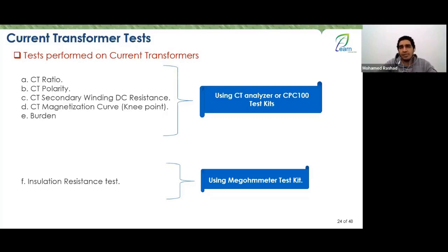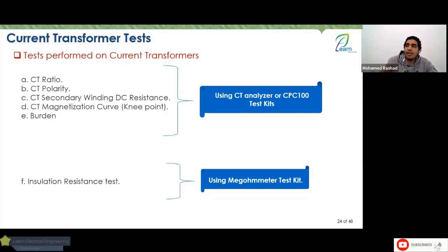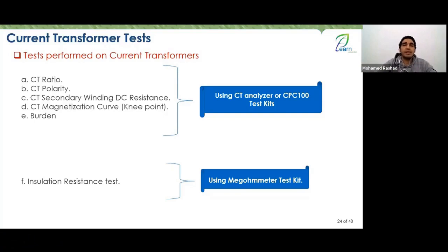And energy is obviously important now because you are billed for it. So do these bills for you represent power or not? Meaning, is it exported power or imported power, i.e. power going out from your bus bar to the feeder, or coming in the opposite way? And this obviously makes a big difference in billing calculations, especially if you're talking about lines between countries or between stations. We calculate the energy exported and imported between the stations.